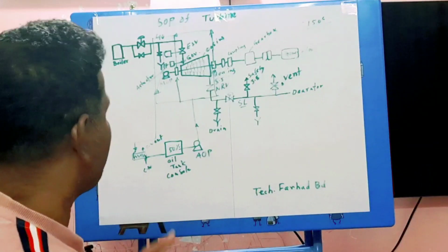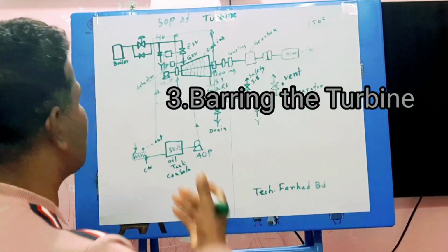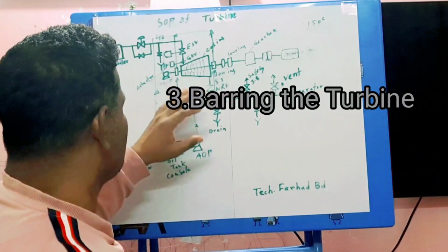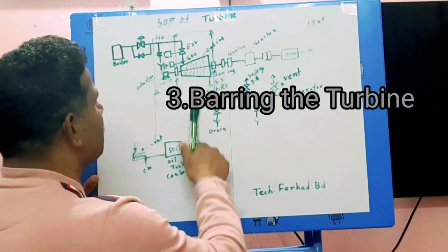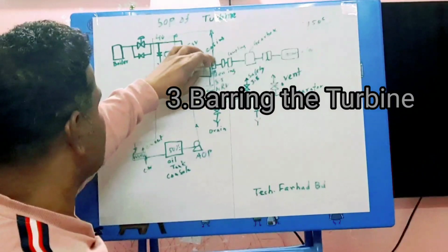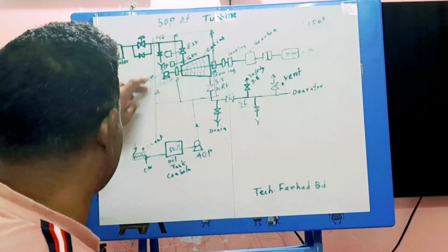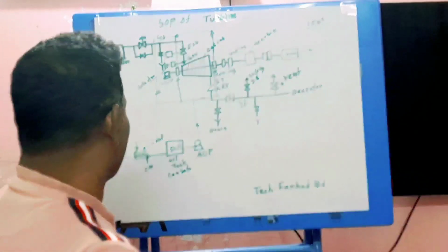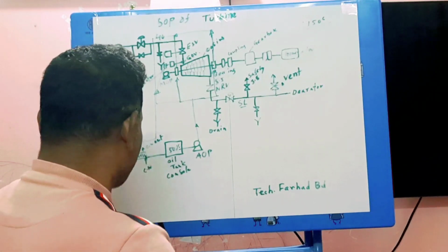After confirming the cooling water system and lubrication system, you can start the turbine. You should also check one thing. After starting the auxiliary oil pump, the oil temperature will increase after discharging from the bearing side. For reducing this oil temperature, you can use the exhaust fan.